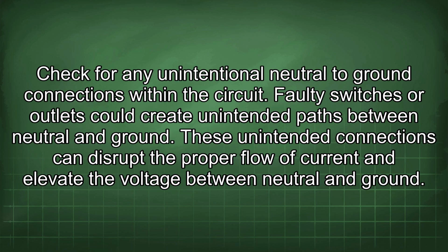Check for any unintentional neutral to ground connections within the circuit. Faulty switches or outlets could create unintended paths between neutral and ground. These unintended connections can disrupt the proper flow of current and elevate the voltage between neutral and ground.